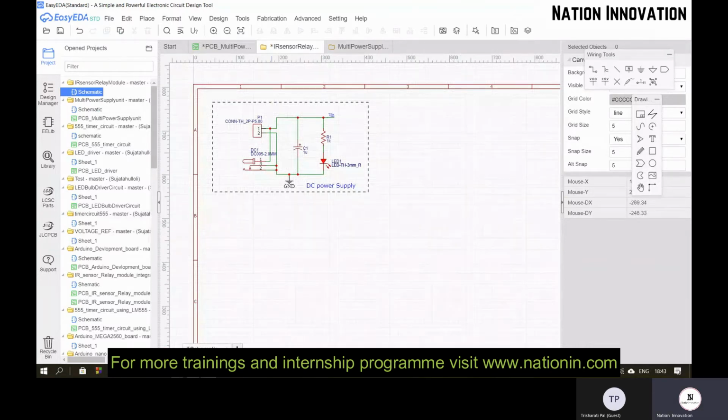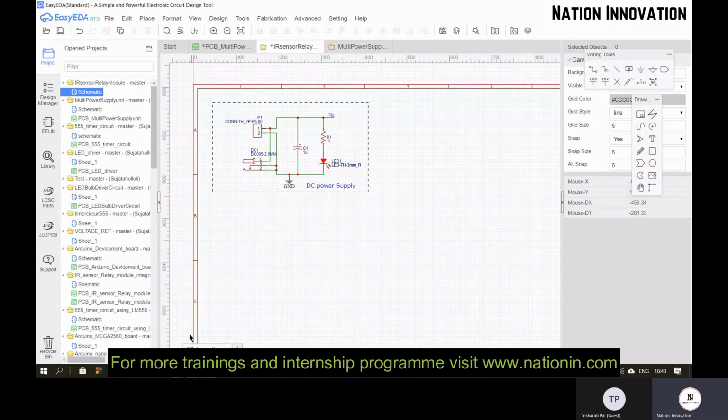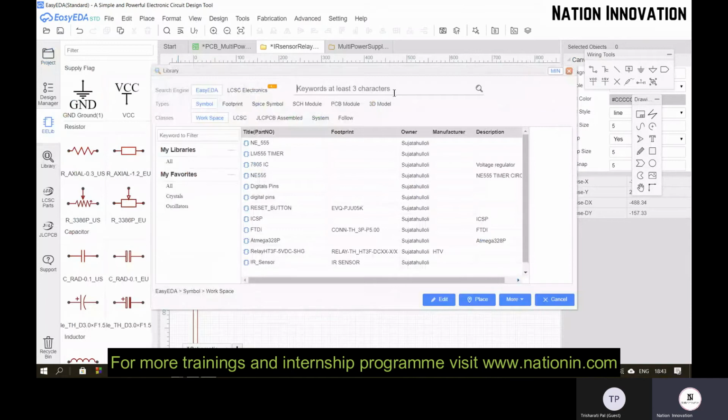In the case of the IR sensor, as I have shown you the design, I will select the components accordingly. Firstly, we need an IR LED and a photodiode. You will not find that in the EasyEDA library, so you need to go to the global library and search for IR LED.